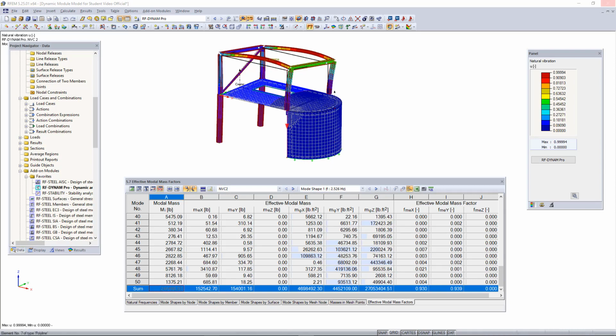Since in the previous videos, we have already determined the natural behavior of our structure under the applied cases and combinations, we can now move on to an RSA. So you can see these results are shown, and after running about 50 mode shapes, we're reaching at least 90% mass participation in each orthogonal direction.